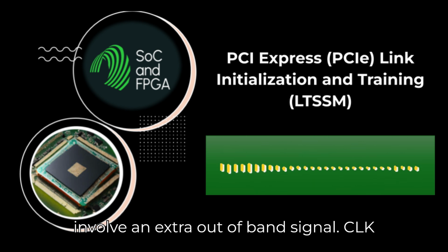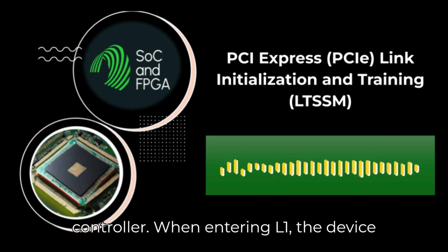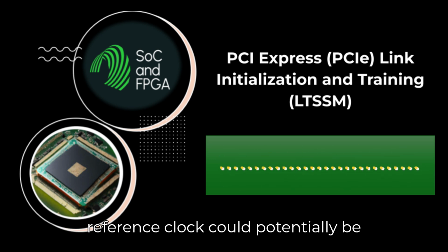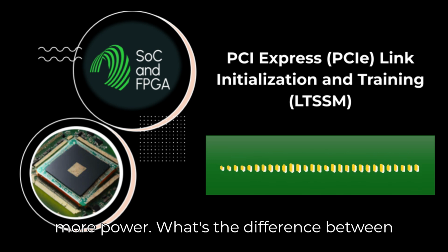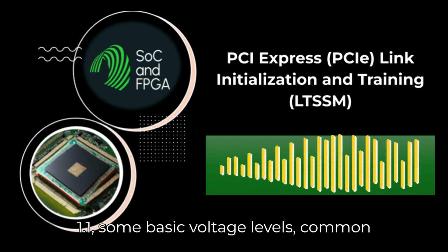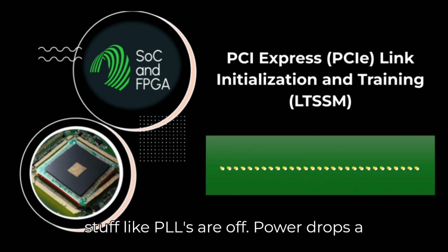They involve an extra out-of-band signal, CLKREQ#, to talk to the system's clock controller. When entering L1 substates, the device drops CLKREQ#, signaling the main reference clock could potentially be turned off. Turning off the clock saves more power. What's the difference between L1.1 and L1.2? In L1.1, some basic voltage levels, common mode, are kept alive, but the high-speed stuff like PLLs are off.